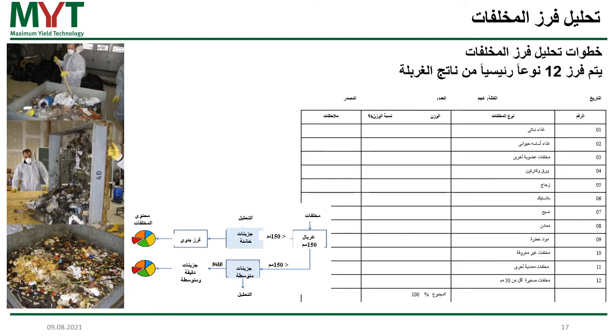So here you can see now the 12 main fractions to be sorted from the screen fractions. We will distinguish between vegetable food, animal-based food, other organic waste, paper and cardboard, glass, plastic, textile, metal, hazardous material, undefined material, other mineral waste, and the fine waste, which is below 30 millimeters.